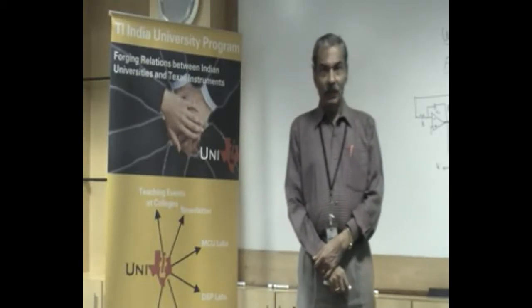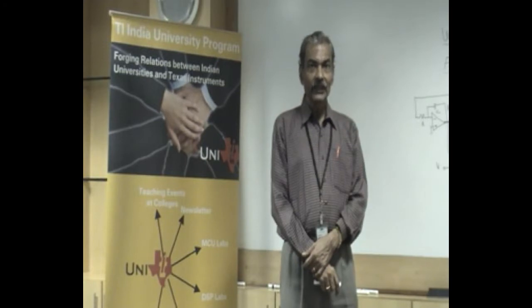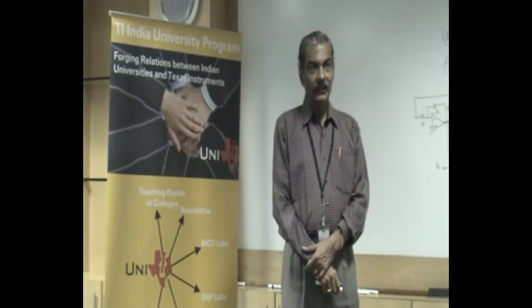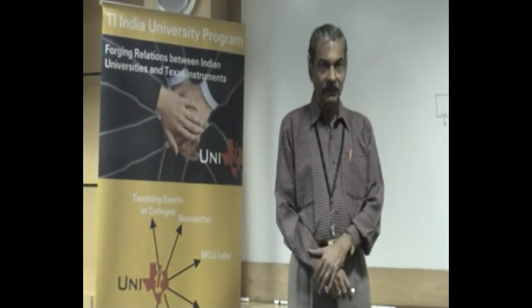Today we'll discuss filters. Filtering forms a very important activity in analog signal processing. We are trying to improve the signal to noise ratio of most of our analog signals after they come from the transducer. So this is the first step towards improving signal to noise ratio, and we need different kinds of filters. One of the most important building blocks in filters is called the universal active filter.